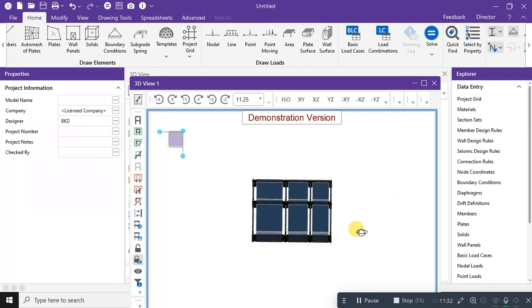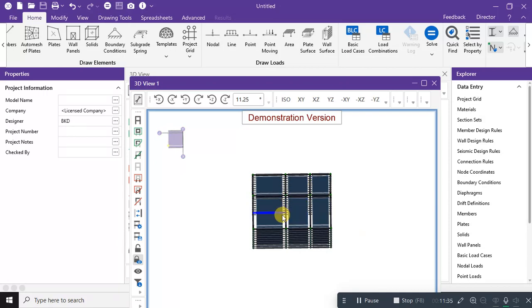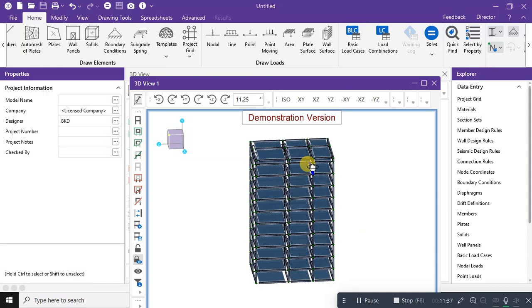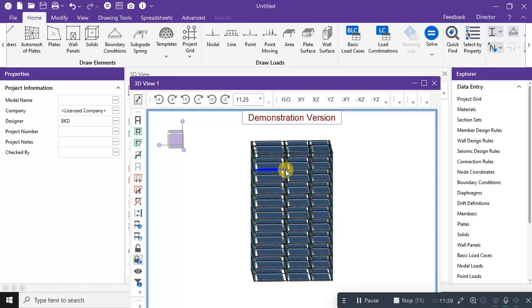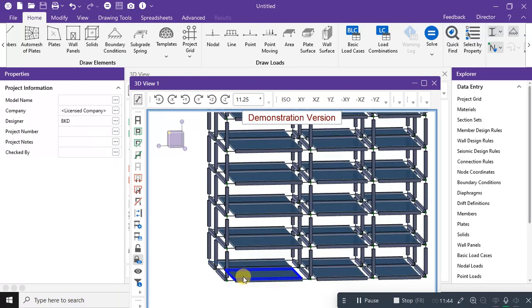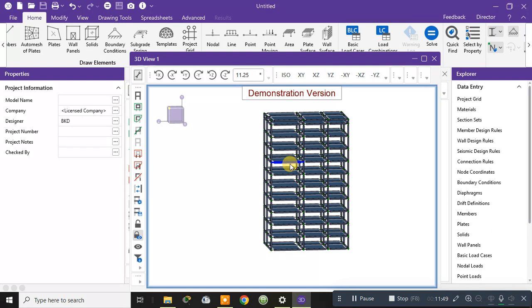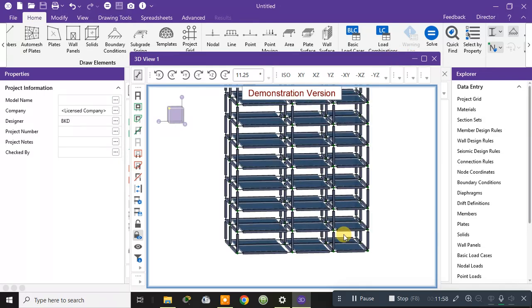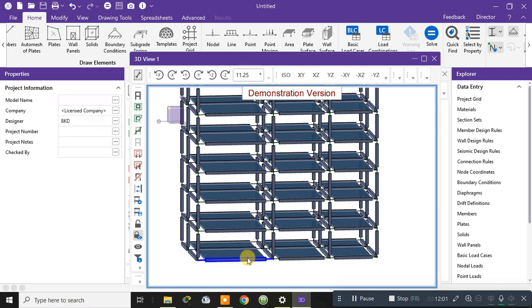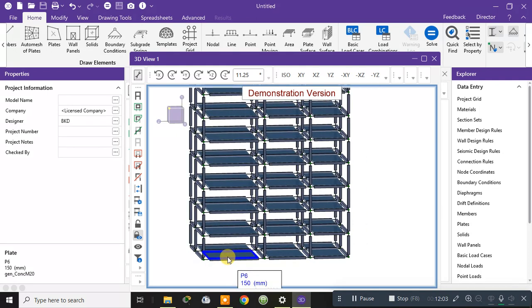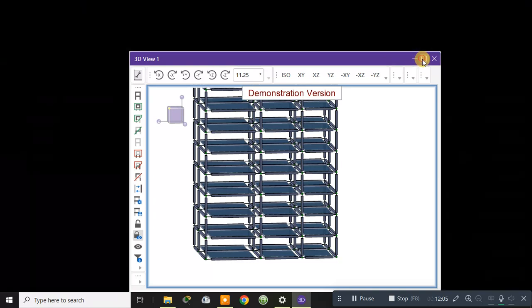See, in all the floors, the plates are being provided. Even in the bottom story, the plates are provided, which I have to remove. So, as you can see here, the height of the building of 11 story, but only the problem is in the bottom floor also the plates are being present. So I have to delete these plates.